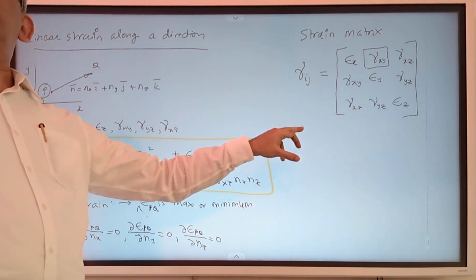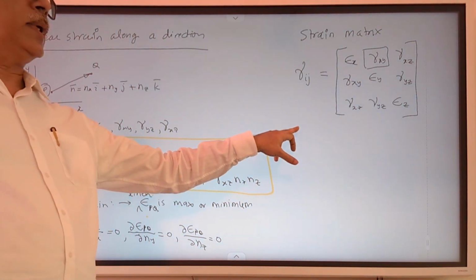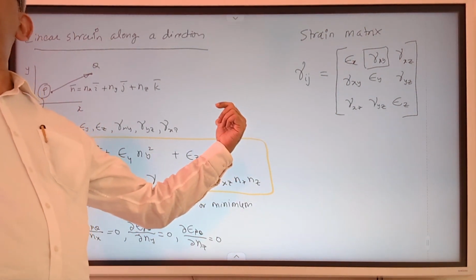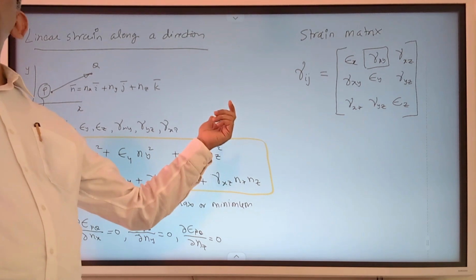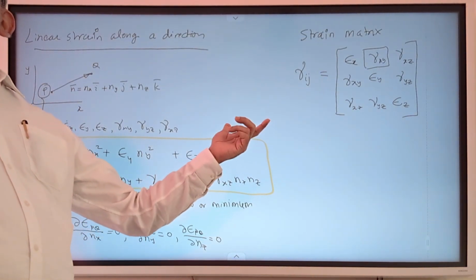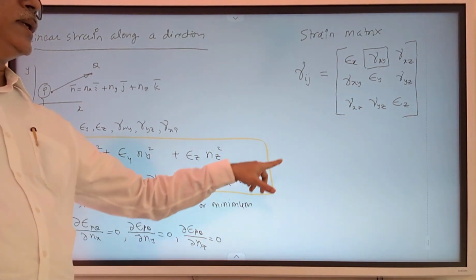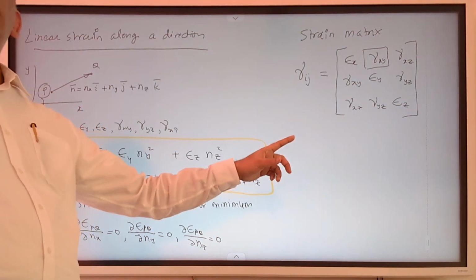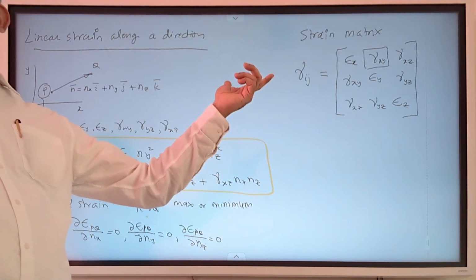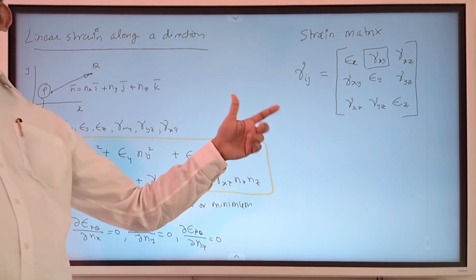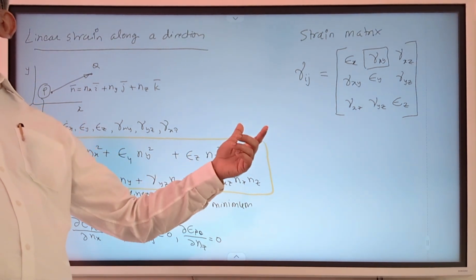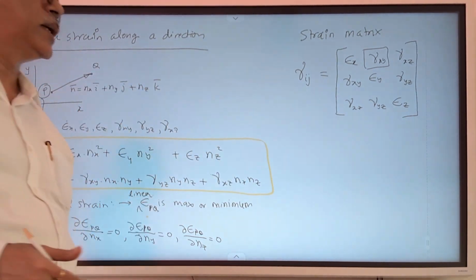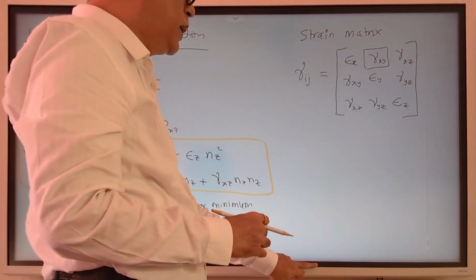Now, if you remember, the equation for the principal stresses was obtained in terms of roots of a cubic equation. In this case, exactly the same cubic equation applies, and instead of stress invariants I1, I2, I3, here we have strain invariants J1, J2, J3. They are expressed almost similarly to that of the stress matrix.